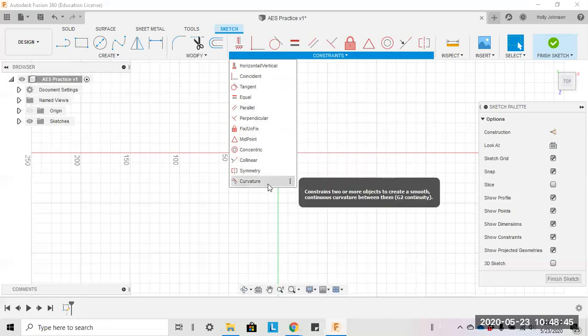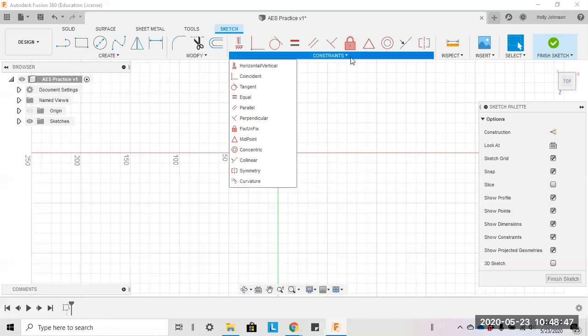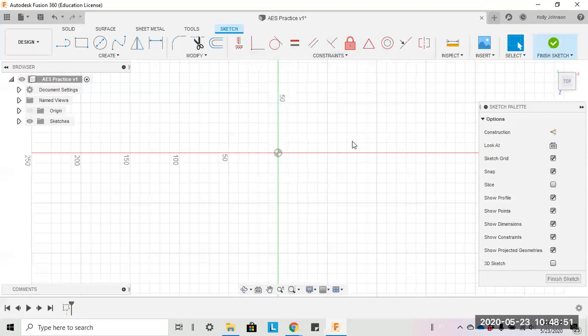You can just do a quick Google search if any of them are confusing you. They're good things to know, and oftentimes if you're trying to move a part and it's not working with you, the first thing that you want to check is the constraints, because generally there's a constraint that you forgot about that's not allowing you to shift something from where it currently is. You'll see that a bit more in the future.